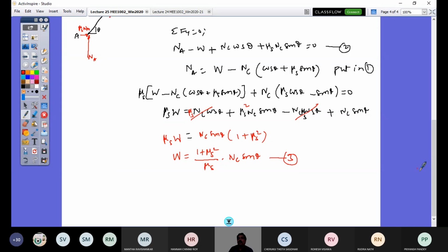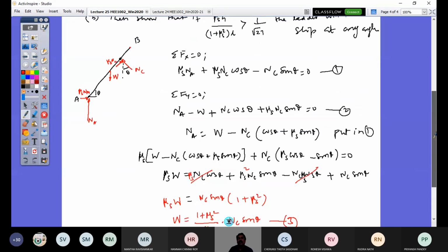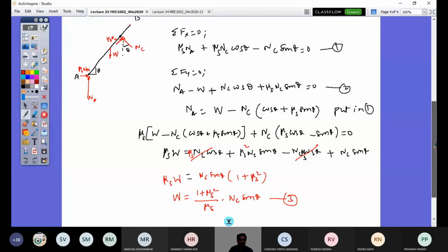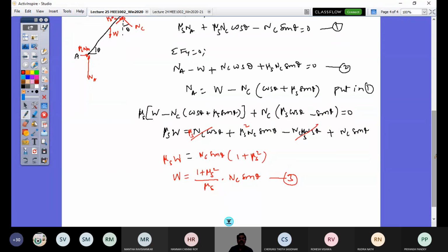I can do that if I apply my third condition of equilibrium, which is moment equilibrium. So let me take moment about point A. Right, point A. If I apply that, you have a class, you can proceed. I would complete this problem and then I will stop the lecture. So taking moment about point A equals 0, I would have NC into this distance AC, right?